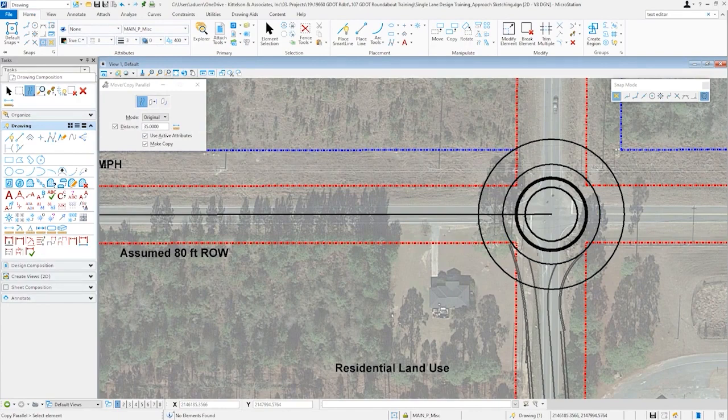I usually develop chicanes about 1 lane width wide, and lane shifts to develop the chicane can be set symmetrical around the center line, or they can be shifted to one side or the other. For this demonstration, we'll shift the approach roadway 12 feet to the right, and there's no set dimension on the shift to my knowledge. That's just personal preference and how I often start my layout. So I will offset the center line by 12 feet, and that will be the largest extent of the chicane as we develop the approach roadway.